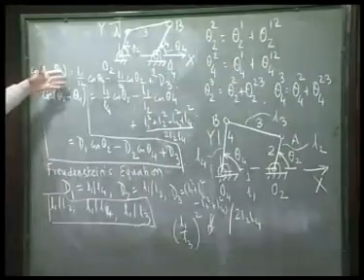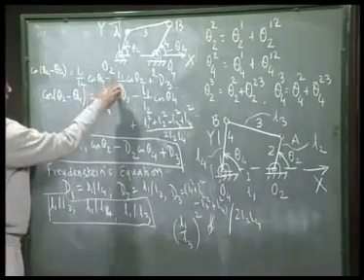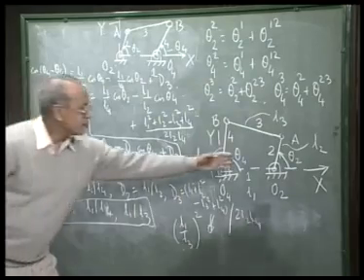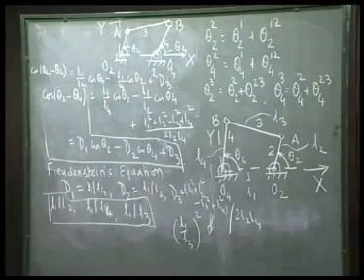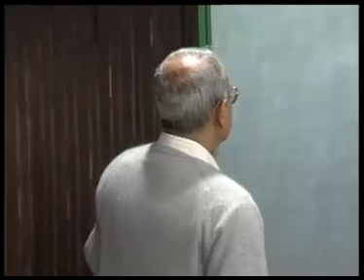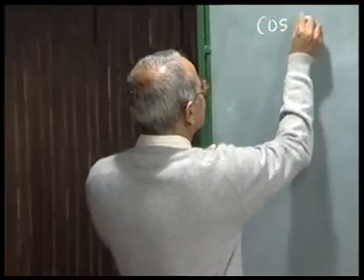So, we define L1 by L2 as one design parameter and L1 by L4 as another design parameter, like the situation we faced here. So, that is Freudenstein's equation and this is Freudenstein's method. As explained just now, for 3 position synthesis, we write Freudenstein's equation in this form.